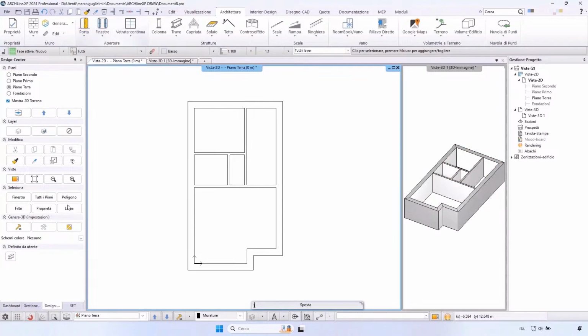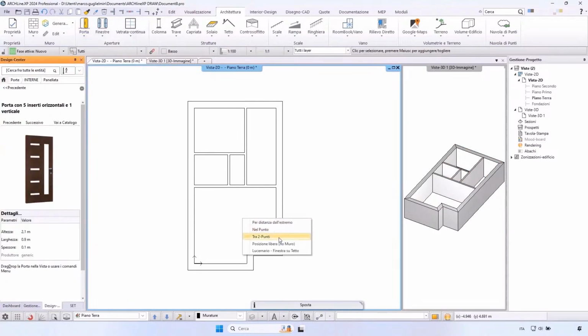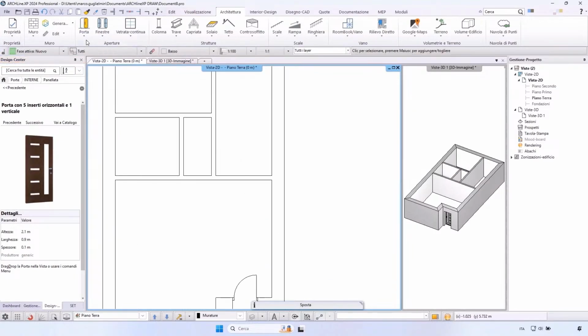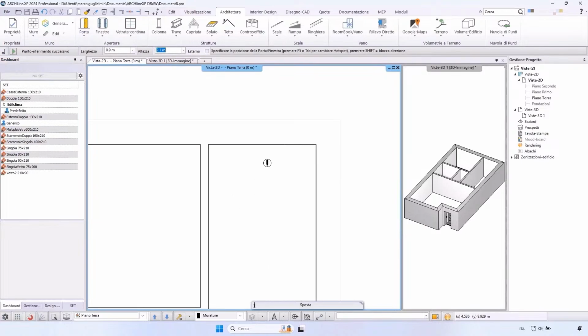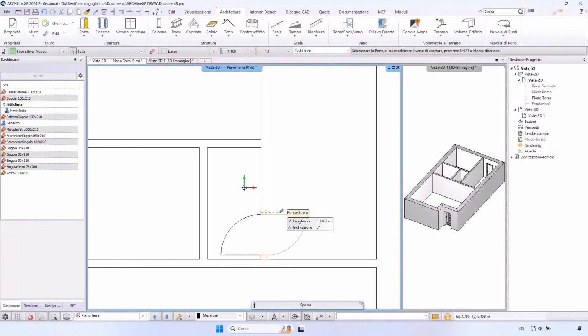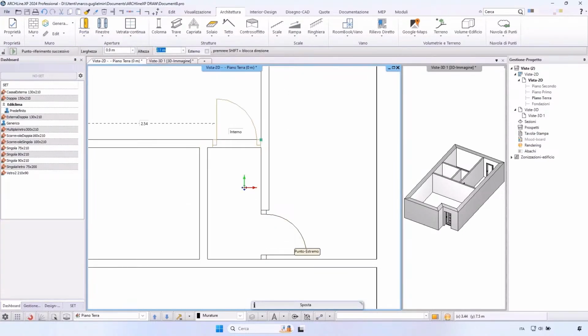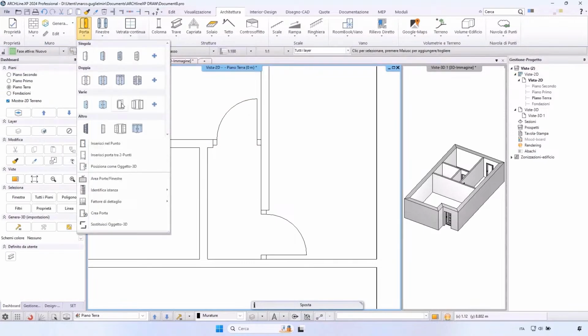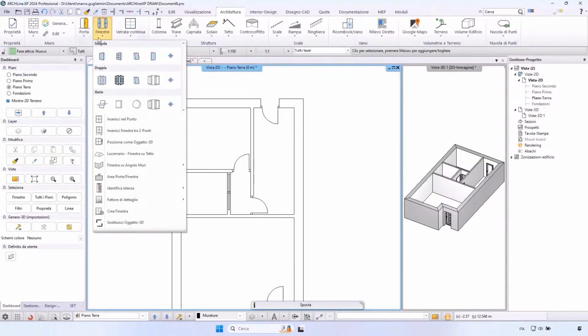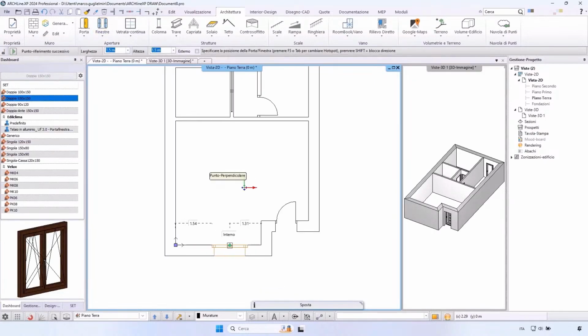The door tool allows the door to be placed precisely in walls and modified if needed. Doors are hosted components to the wall. After selecting the relevant door type, you can specify its location on the wall. ARCHLine.XP automatically cuts the opening and places the door. The door is attached to the wall, so it's placed on the wall layer.